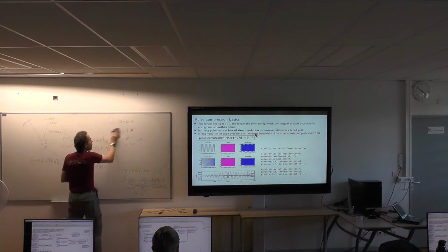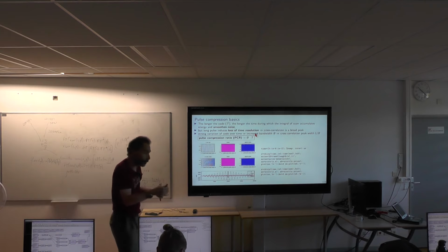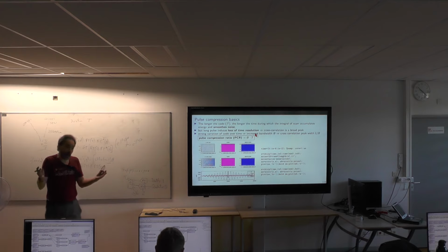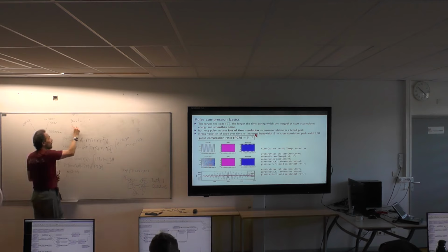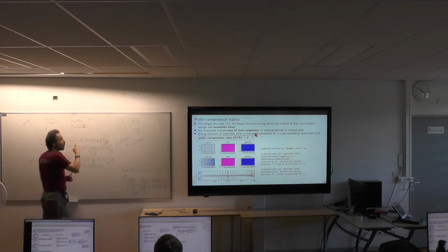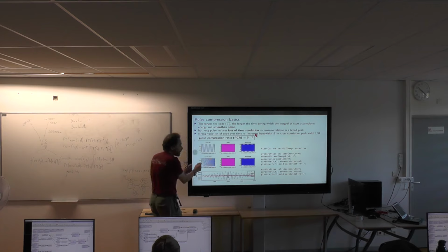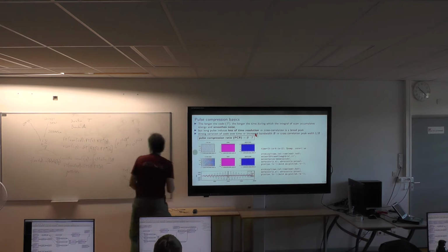So we have these two dual requirements on the signal that we broadcast. On the one hand, we want to have averaging duration. So we want a long duration to average out the noise. But on the other hand, we want to have some bandwidth, because by using a broader signal, a broadband signal, we avoid mismatching the end of a signal with the beginning of a signal, and so the broader the bandwidth, the narrower, the sharper the correlation peak.